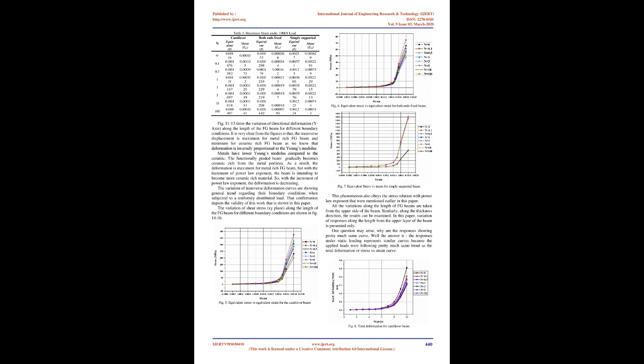The mechanical load was applied on the metal surface. The FGM beam was modeled in ANSYS. The mesh size of 1 mm is taken in this paper. Total number of nodes is 2,342,610 and the total number of elements is 500,000. Figure 4 shows the modeling of an FGM in ANSYS.